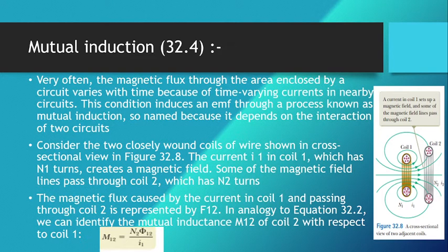And its unit we can take from the law, which will equal volt times seconds over ampere. Volt times second, we can say it's called a weber, so it equals weber over ampere, and volt over ampere is equal to ohm, so it's equal to ohm times second. And all of this is equal to a unit that is called henry, after a scientist.